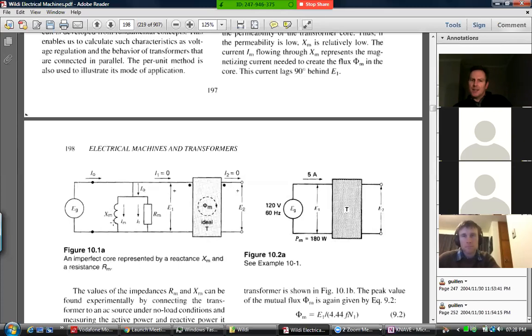We will see later. This guy does cause a little bit of a secondary effect in terms of power loss because there's another resistor element coming in our circuit over here due to another effect that we're going to look at. And so to get the current going through here, it's got to go through a resistor first. So all the extra current that flows through here goes through a resistor. So you get a bit of extra I squared R loss in that resistor, because of this extra current getting pulled through here. But in through here itself, it's just storing and giving it back, storing and giving it back. But this side is wasting real power.